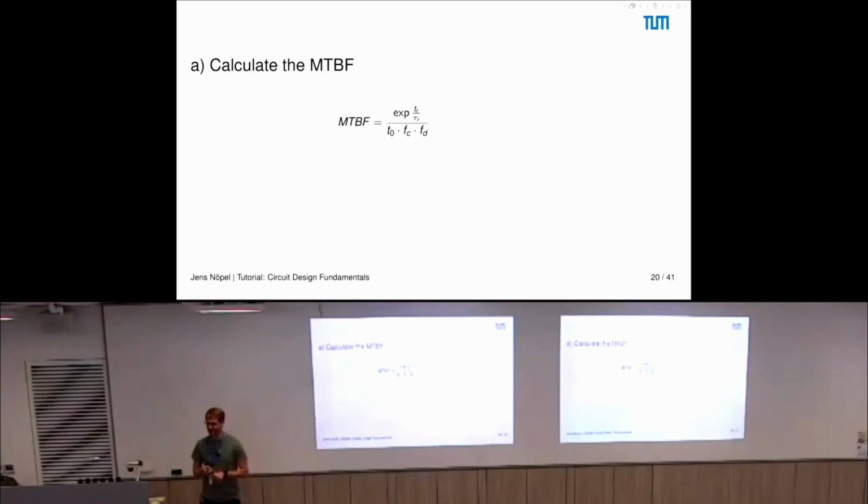So it could be the case that we change the data in signal at a point in time where it shouldn't be changed, which leads, or could lead, to metastability. Now, if we think about FD, this is the frequency on which our UART is running, and usually that is very, very slow.